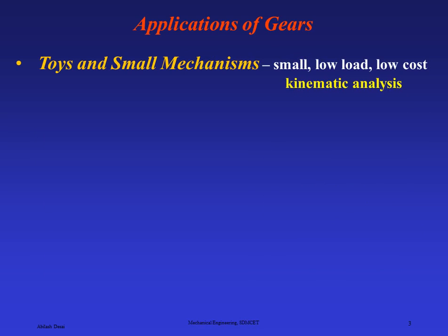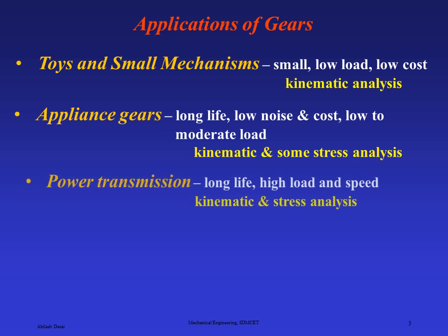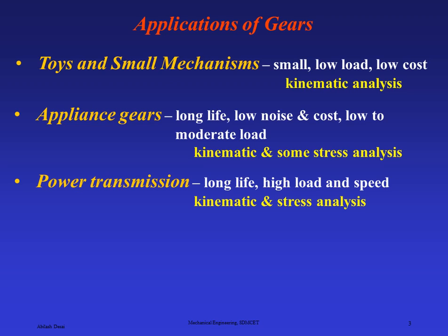Applications of gears can be seen in different toys and small mechanisms, where it is for small, low load and low cost use, and kinematic analysis. Appliance gears are for long life, low noise and cost, and low to moderate load. Kinematic and some stress analysis can be done on these. Power transmission gears are for long life, high load and speed.